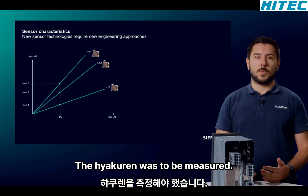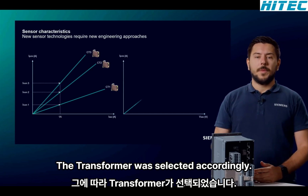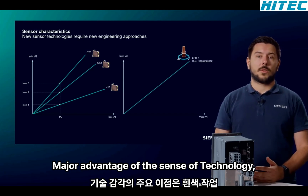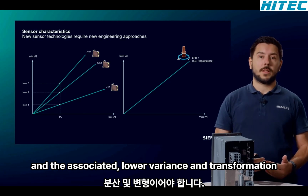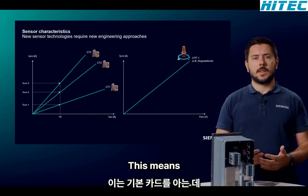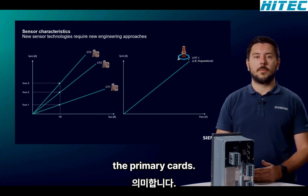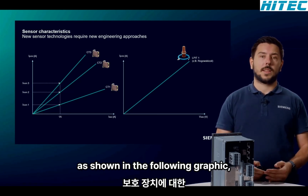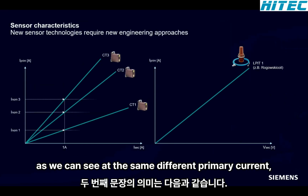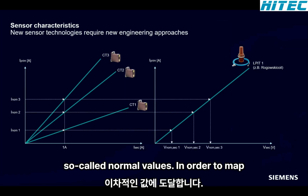If a higher current was to be measured, the transformer was selected accordingly. The major advantage of the sensor technology should be the wide working range and the associated lower variance in transformation ratios. This means that a Rogowski coil can be used for a wide range of nominal primary currents. What this circumstance means for the protection device is shown in the following graphic. As we can see, at the same different primary currents, we reach different secondary so-called nominal values.